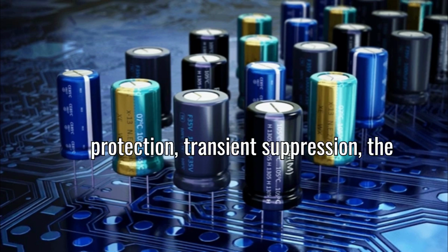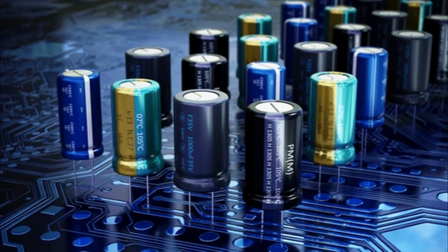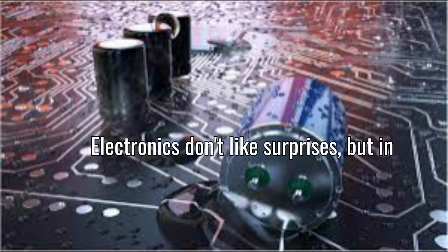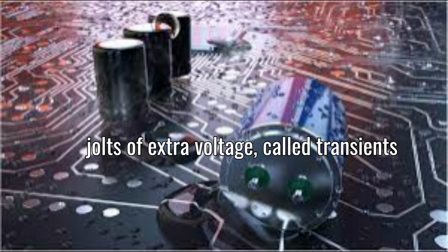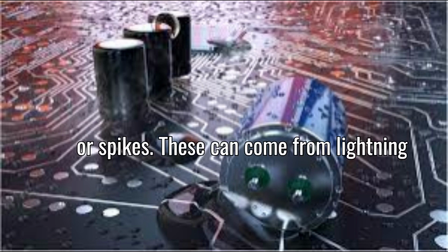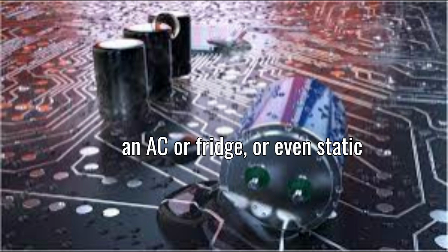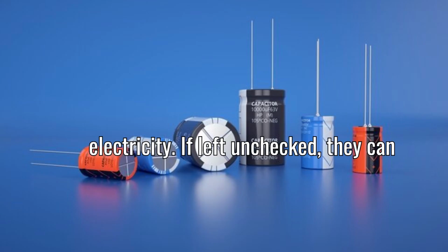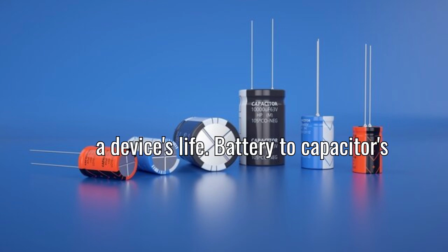And number 7 is protection, transient suppression. The problem: voltage spikes. Electronics don't like surprises. But in the real world, circuits face sudden jolts of extra voltage, called transients or spikes. These can come from lightning strikes, switching large appliances like an AC or fridge, or even static electricity. If left unchecked, they can burn out chips, crash systems, or shorten a device's life.